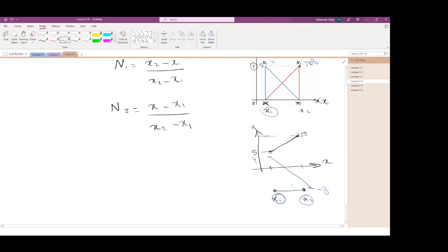Any pattern of displacement can be recovered as long as the pattern of displacement is going to be a line. And this is the strength of the shape functions. So they can basically reconstruct the entire displacement within your element just using the value of the displacement at the nodes. All right, I'm repeating this because I think this is pretty much the focal point of this lecture today.